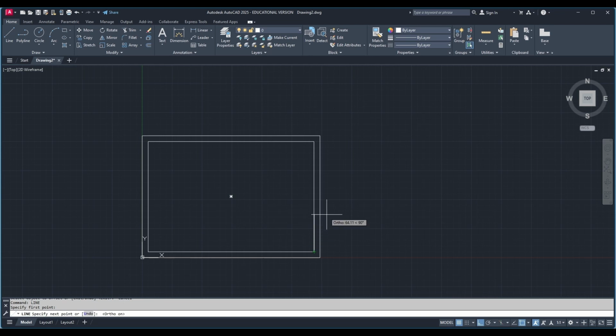So I will position the line in which direction I want to go, and then type on the command window the dimension. Here I have typed 50. So then hitting enter, I will get that line. Again, in the other direction I am positioning and then typing the dimension 150, enter. Then coming back down, and I am completing by hitting escape.